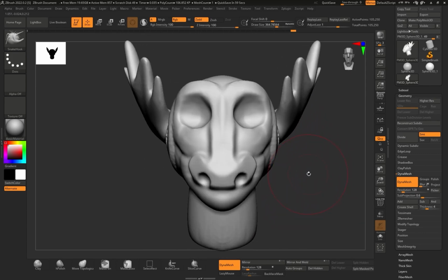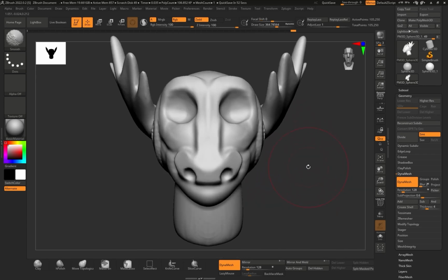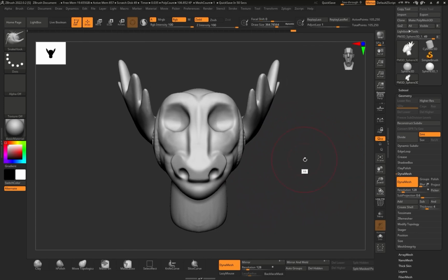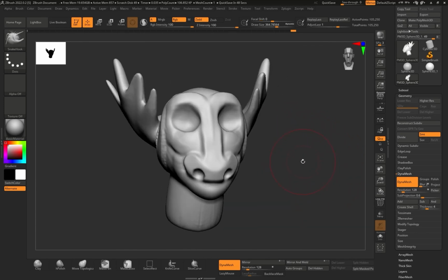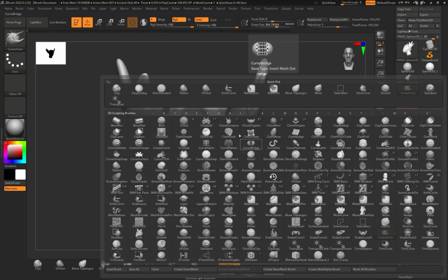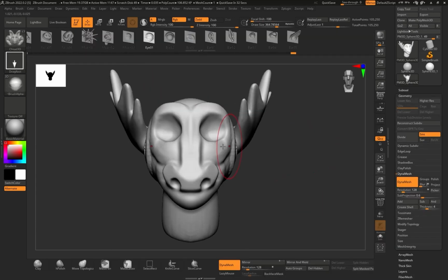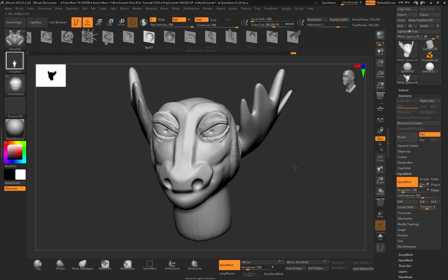And now we're ready to add some details, like some eyes, for instance, and some horns as well. The brushes that we'll use for that are the Chisel 3D and the Chisel Creature brushes. They are located in the first row of the brush menu, and if we click, let's say, Chisel 3D and select the eye and we drag, we can see there are eyes on the model.